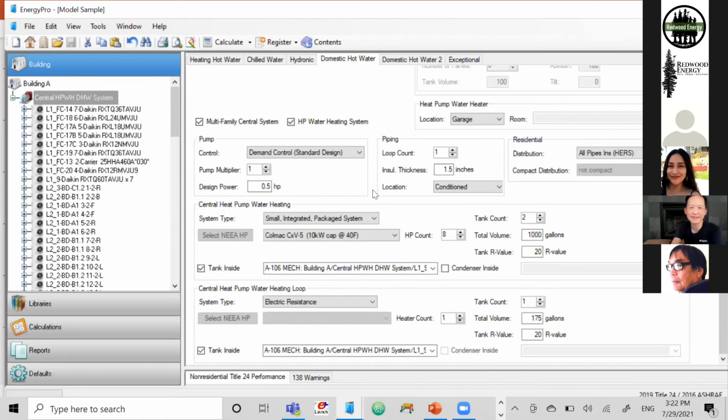But for some reason, there were unmet heating or cooling load hours in one space, and it wasn't passing just for that reason. So it still puts that zone in the report, flagging that it has excessive unmet load hours, so that you know we need to go back and fix it. But it does take away that not-complying margin.